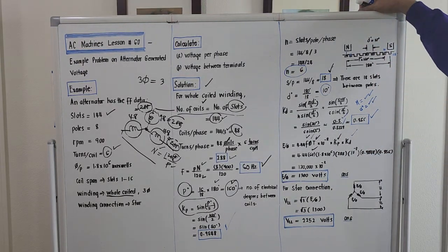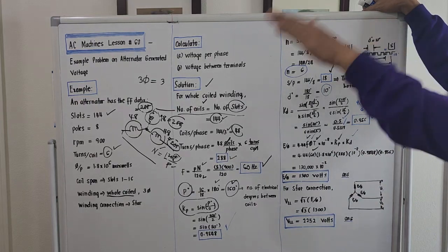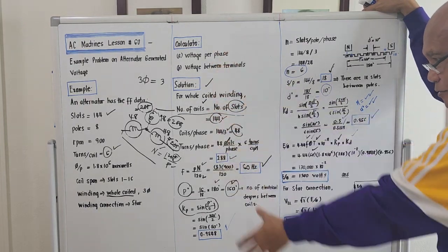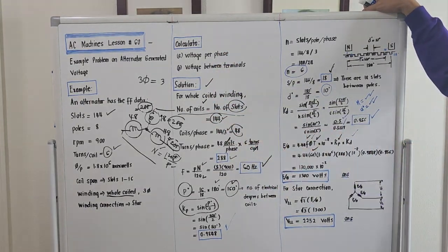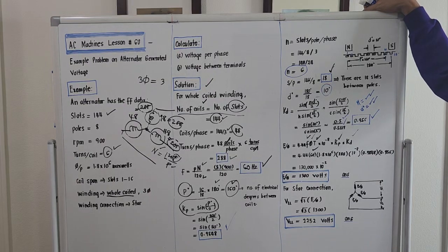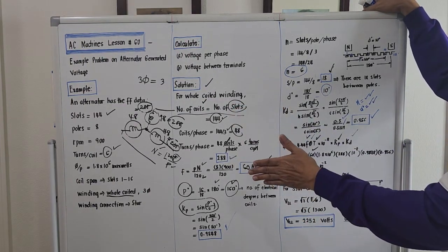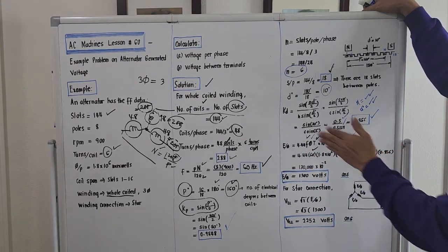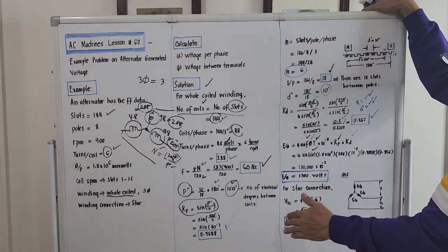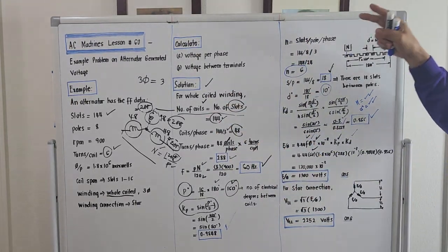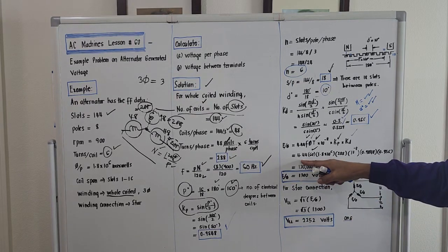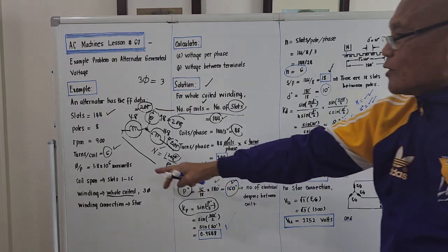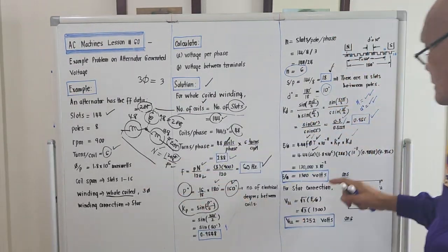Okay, substituting values now. So this is now a direct substitution problem after the so long solution on how to bring out the other parameter, right? That's always the case. Because if all the values are given, there will be no challenge, right? So in the computation of all the parameters here, we needed some concepts in this study of alternators. So substituting values now, it should be 4.44, frequency 60, the flux is given as 1.8 million Maxwells.